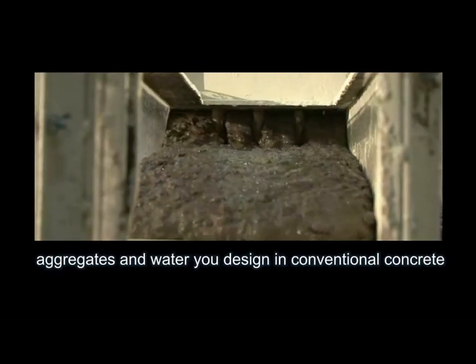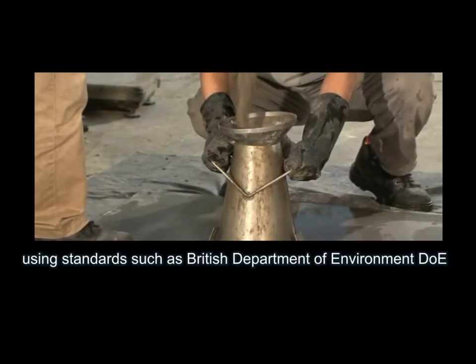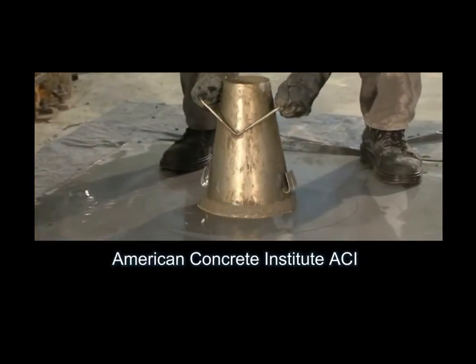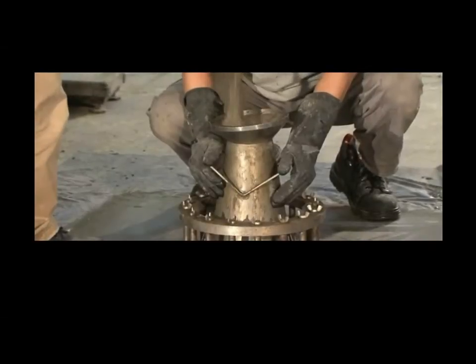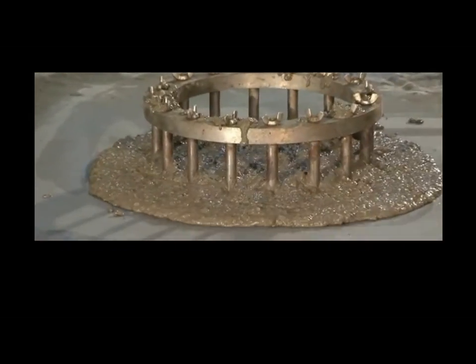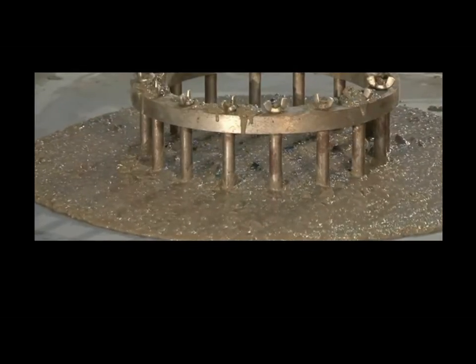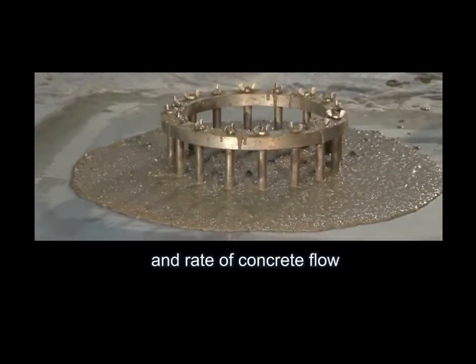Different to cement, aggregates and water you design in conventional concrete using standards such as British Department of Environment, DOE, American Concrete Institute, ACI, or absolute volume approach, SCC does not have a standard design method. It is mostly based on trial and error experience and feeding test data back to the design. The major purpose of SCC is to increase the ease and rate of concrete flow.